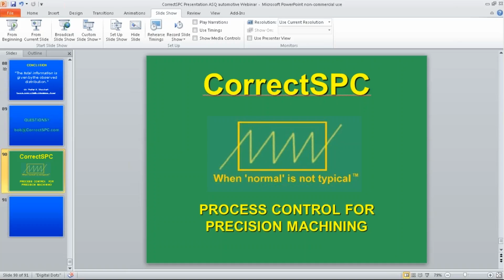It's going to stop at that limit. And if you try to use the Gaussian curve or normal distribution calculations, they extend beyond that, and that's not physically possible. Whereas if you get into some of the other distributions, such as the beta or Weibull, they actually stop at that limit and are a much better model of that variation. And then I compare those to the specification. Now, how well does a model distribution of that data best fit between the specification?